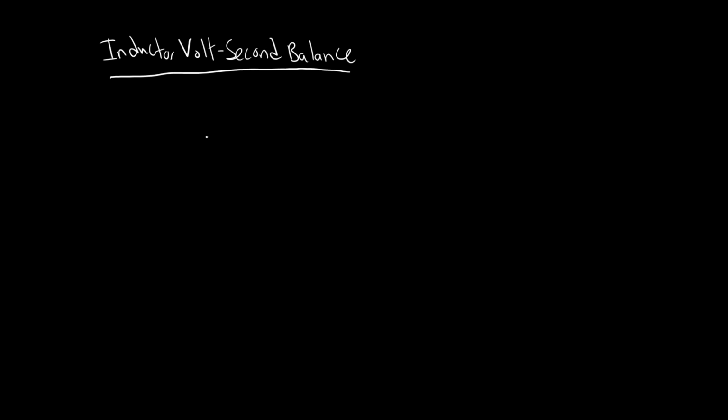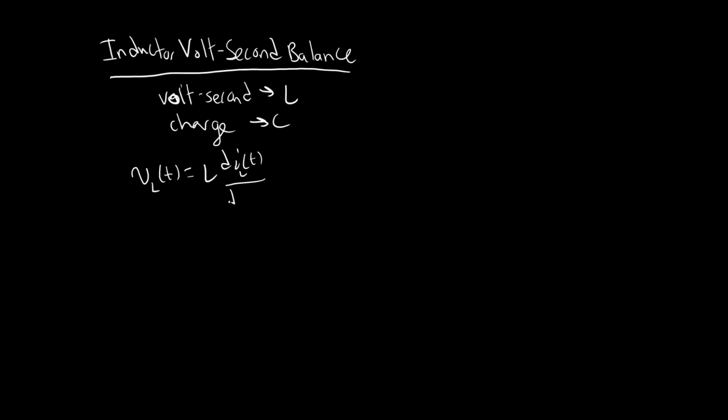Well, to understand what volt-seconds are, first, an analogy. Volt-seconds are to inductors what charge is to capacitors. I'll just write that out. So you can think about that while we write some equations down, right? So the equations are very simple, right? We can think about the governing equation of an inductor, right? V L of t is equal to L dIL of t by dt.